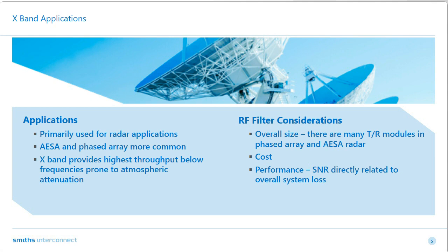These systems can use hundreds to thousands of transceivers in their systems. These systems must limit size and weight to remain practical. One of the enabling technologies for radar applications in this band is the high power available with GaN MMICs. The other components required to support the transceivers operating in the X-band also need to be small and cost-controlled to